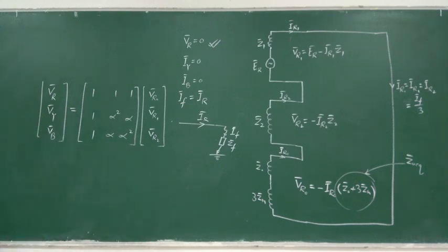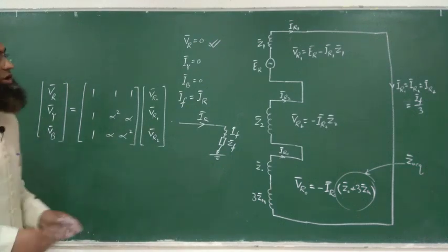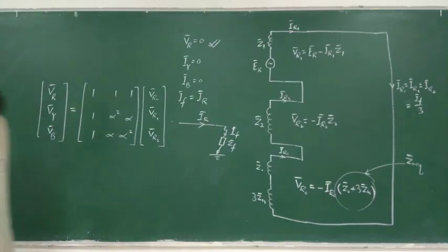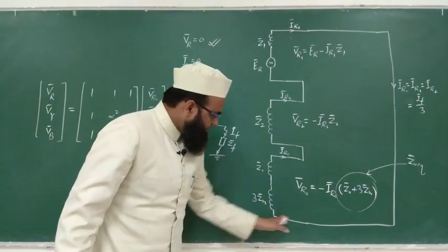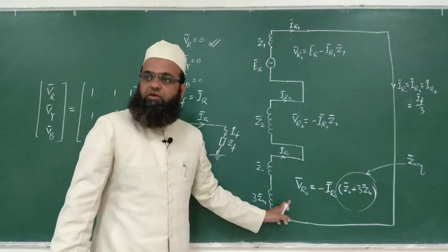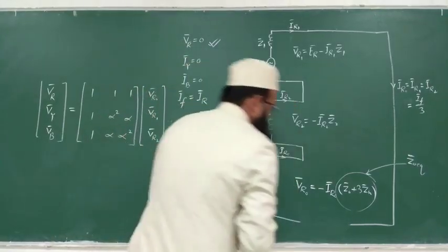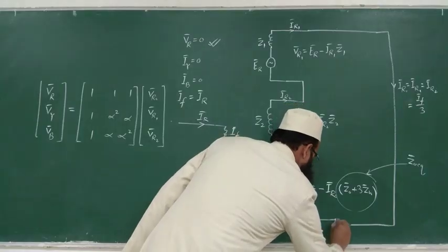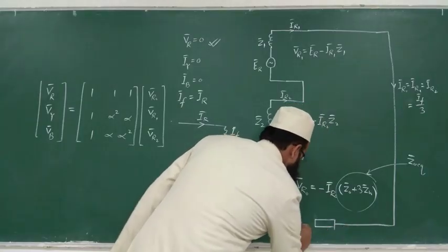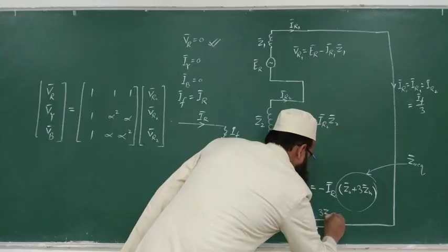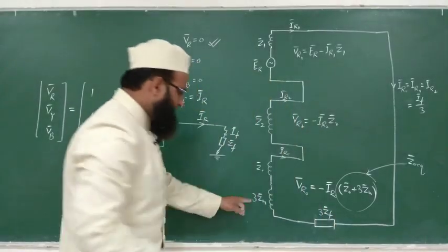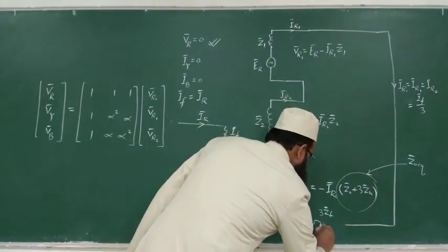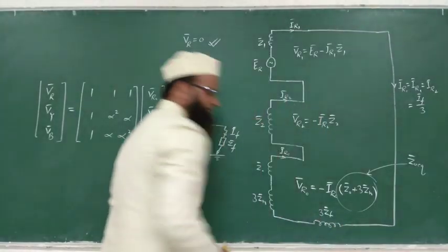Okay, let us solve one problem quickly. And how to reflect that ZF, fault impedance, in this network? That will be connected somewhere here in zero sequence network. So you may write corresponding reflection, just represented by this symbol, 3 ZF, like this, 3 ZN, whichever representation you like, is not it?